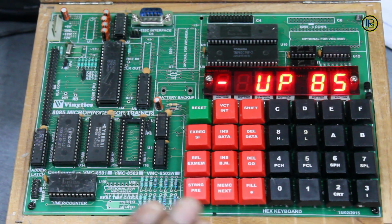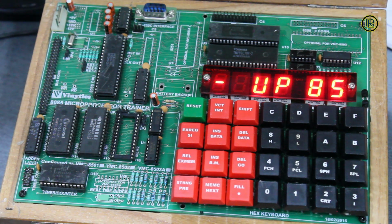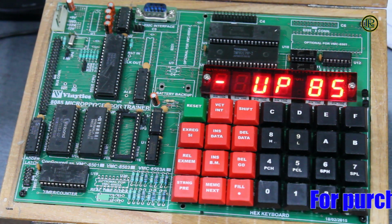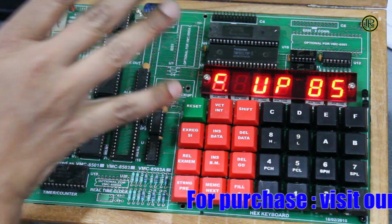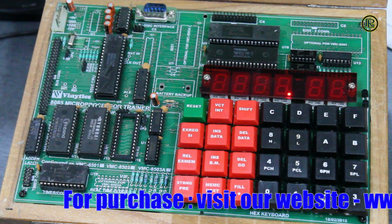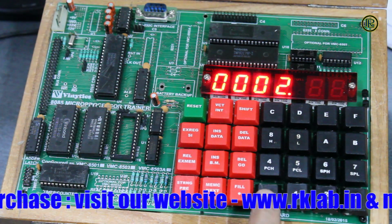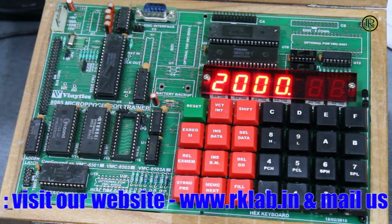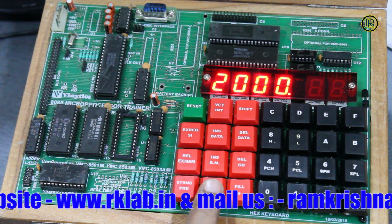Okay, this is our 8085 trainer board. Let me first show you how the memory addresses are shown here and the corresponding data saved here. I am resetting the whole system and then retrieving the memory location. Suppose I start at memory location 2000 and check what data is stored inside.